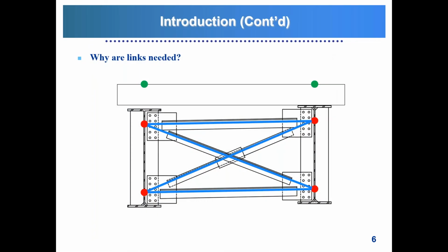For example, here is a cross section of that same bridge. Again, here at the top, we have the insertion point of this plate girder, and then we have the cross-frame members. So even though if you turn on the 3D rendering in Midas, it will look like these nodes are touching that plate girder.